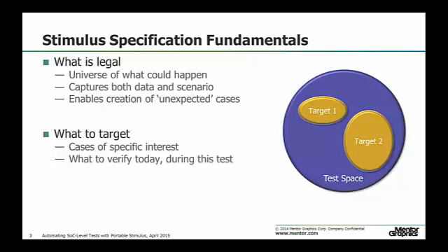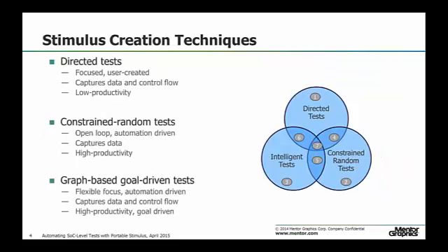We are not specifically modeling exactly what's going to be tested. We're not saying do A, then B, then C. Rather, we are saying that, okay, we're interested in particular combinations of A, B's, and C's. But for now, we don't care about D and E, so they can be left randomized. And that way, we can systematically target the verification goals that we are specifically interested in.